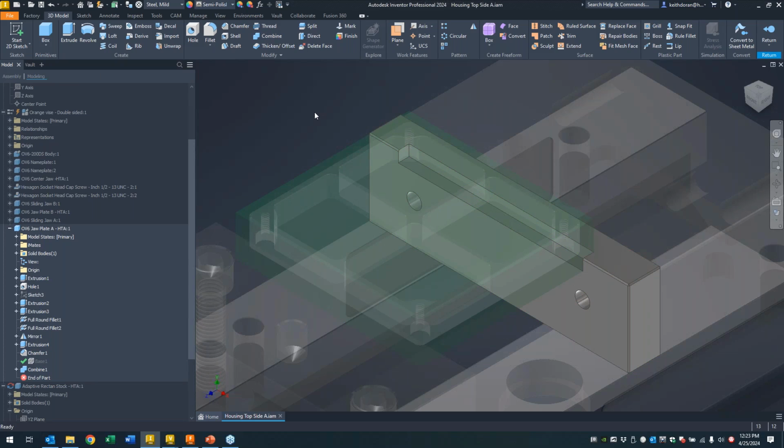Now, from here, I could continue this process, right? Going in and maybe putting in relief corners, modifying these by pushing them or pulling them by some small amount to make sure that there's enough clearance for that component to fit in there. In the event that my stocks aren't all perfect, whatever other additional edits I might want to make to this solid. But that first step is really, really helpful, right? Being able to use the copy object and the combine command simplifies the creation of these, and it ensures that it's exactly the same size from the assembly into this model.